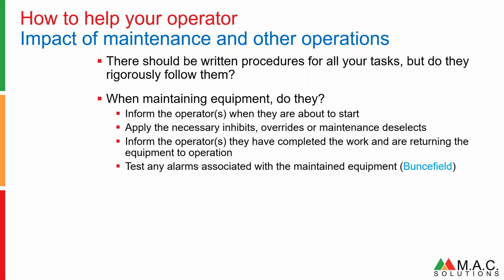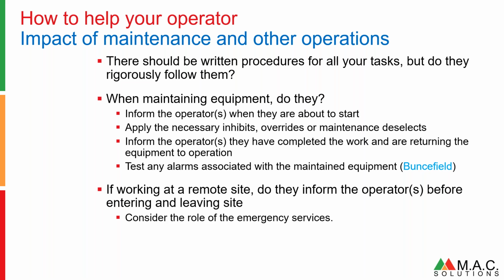That was because they didn't test the alarm. Finished the job, went away. The operator didn't know they'd finished. There were a lot of other things happened. It wasn't just that particular thing, but there were a lot of other things came into play there. But the operator didn't know. He had no way of knowing because the level alarm didn't actually work. It didn't generate an alarm because it was out of position.